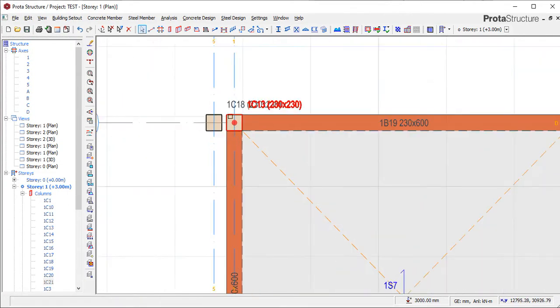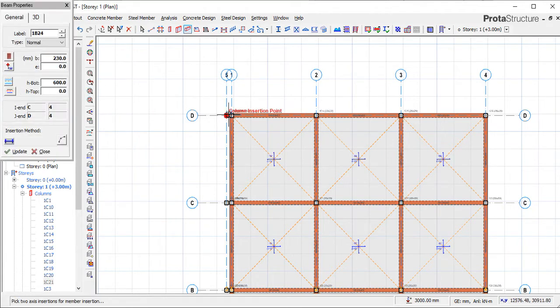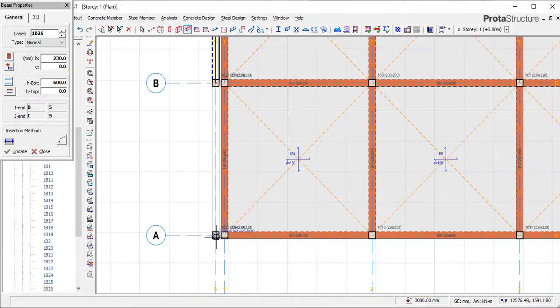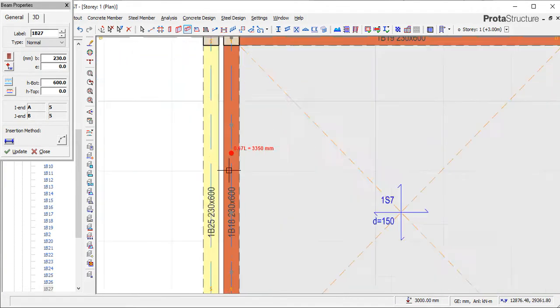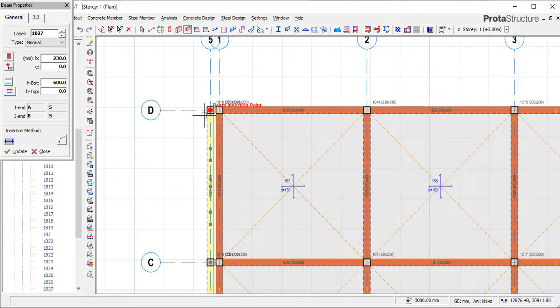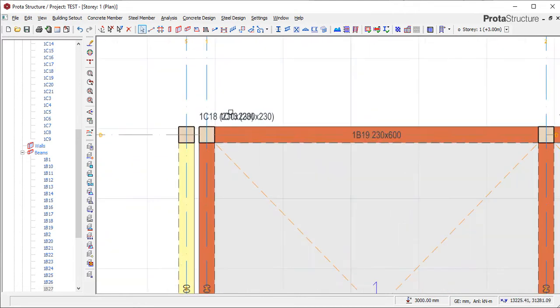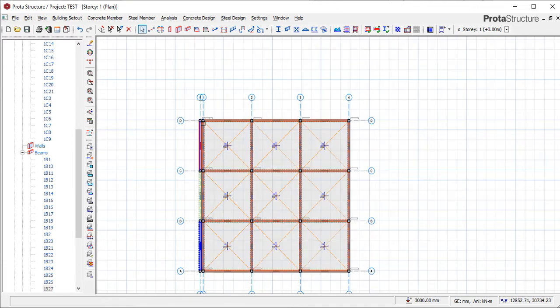Especially when you are doing expansion joints, you can create your double columns, take your beams and run them through, connecting them together. This is how you create your double columns. So the main thing about creating double columns is the grid lines, your spacing in between the grid lines. So if you offset and get that exact space between your columns, then you can easily create double columns.